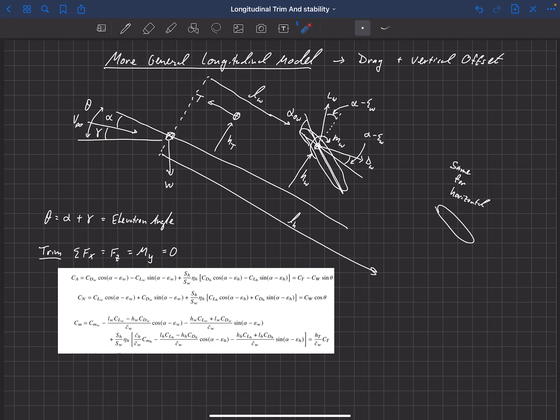We're accounting for both the horizontal and the main wing in here. And then remember that we're aligning this axis, our fuselage reference line, which is the direction of the axial force, that is aligned with the thrust. And I call this the coefficient of thrust. That's just C sub t, defined as thrust over 1/2 rho v infinity squared S_W.